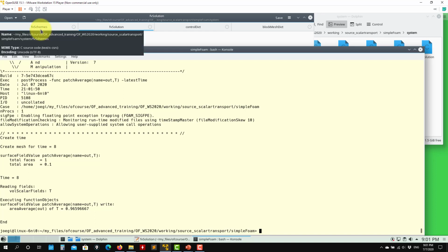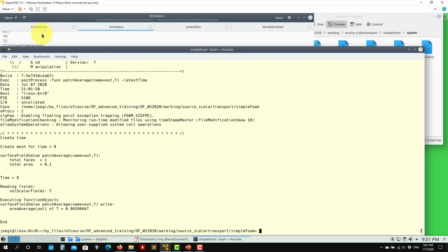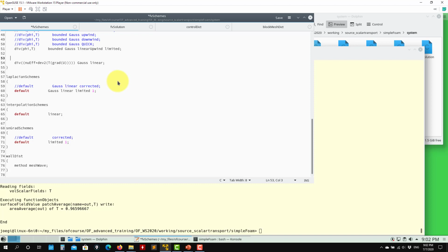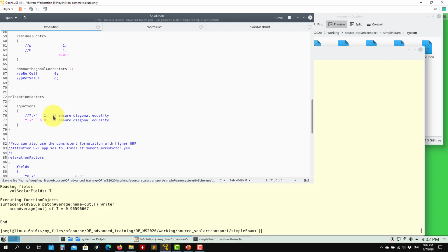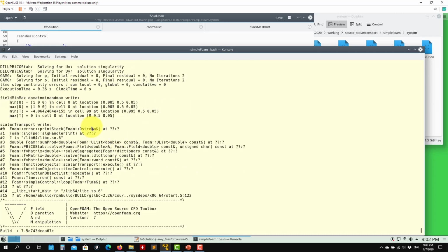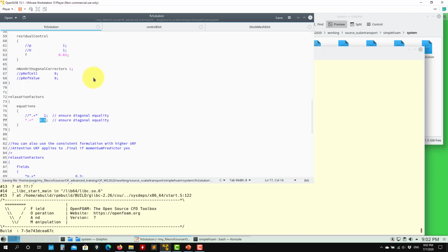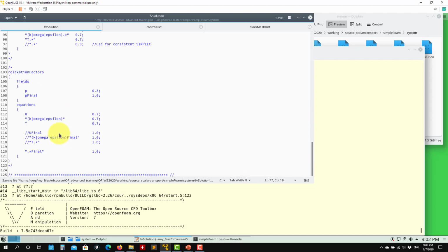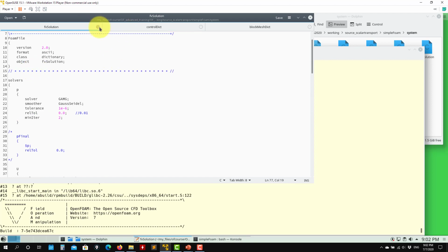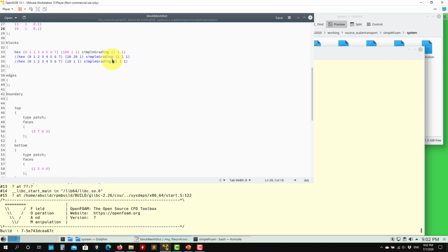And now let's move to the next case that will be working the same problem using pimpleFoam. Let me just see here a little bit. Saving this one here. Again, as you put here over-relax, it will diverge. Or it will converge to the wrong solution, but actually diverge. So see here, it diverged. Commented 0.1, 1. And Control D, everything enabled, and the mesh.